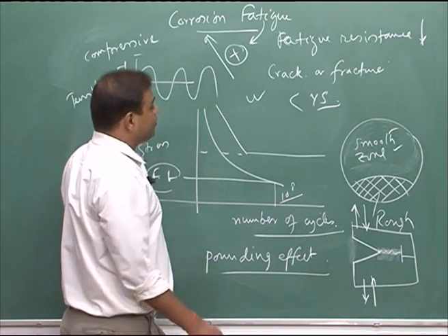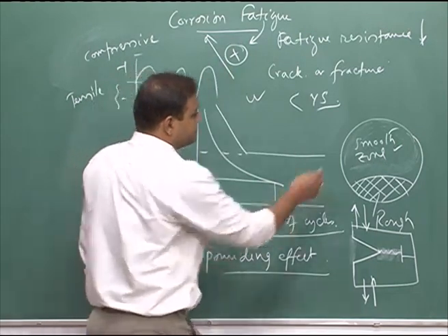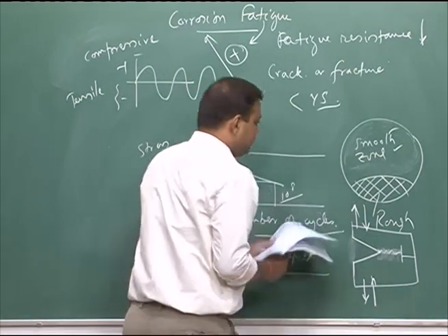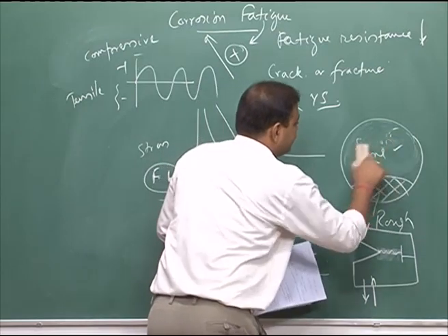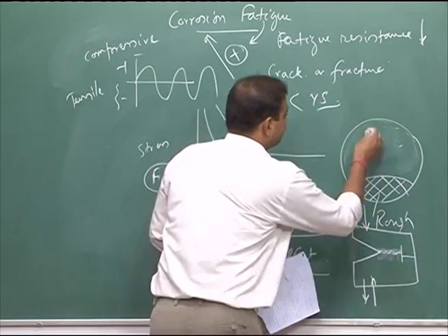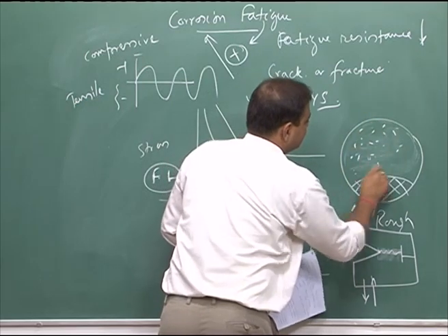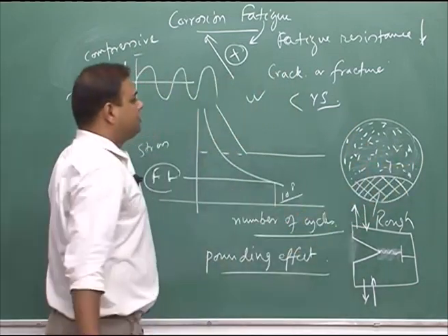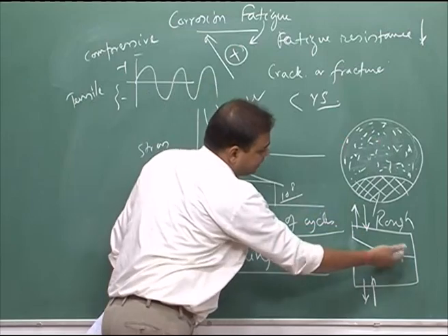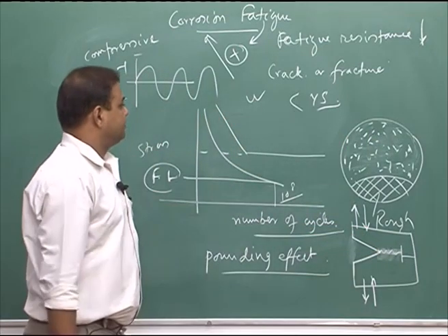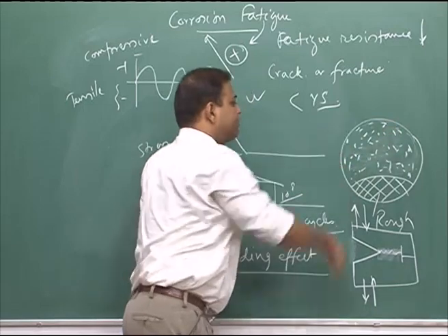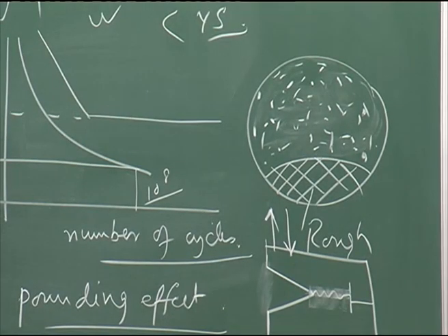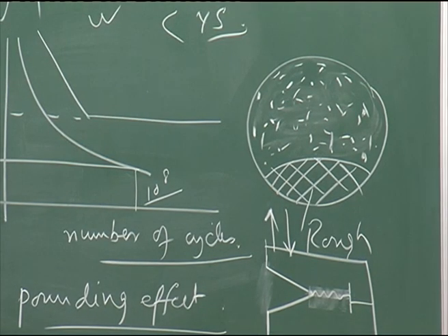Now, during that process this surface would always be rough. At the same time, if you have corrosion together with the fatigue phenomenon, this smooth zone would not look like a smooth surface; rather, you will have corrosion debris or corrosion product on this material. For example, those are corrosion products. These corrosion products would form on this zone where you have crack propagation via fatigue action as well as corrosion happening. So, you have the corrosion deposit. This is the fracture surface appearance if we have corrosion fatigue.